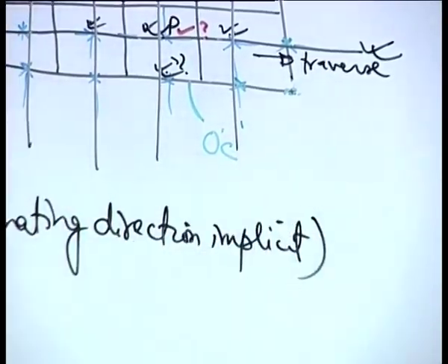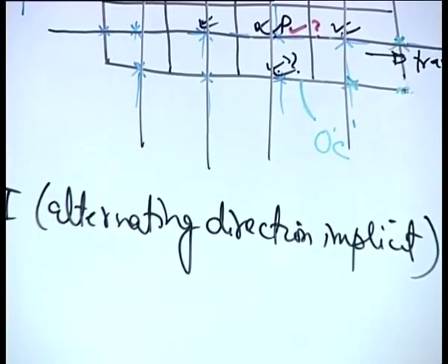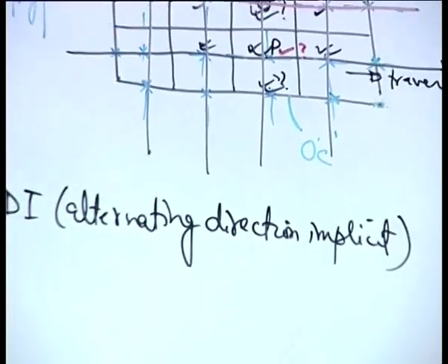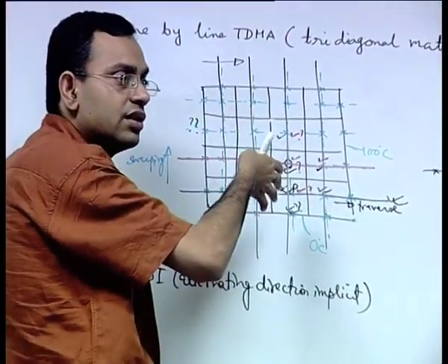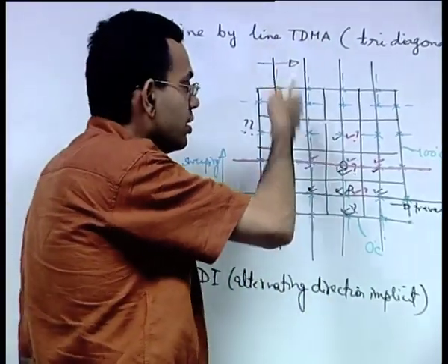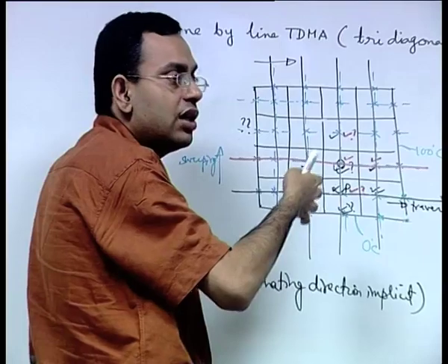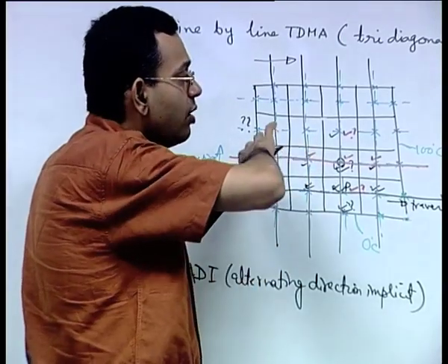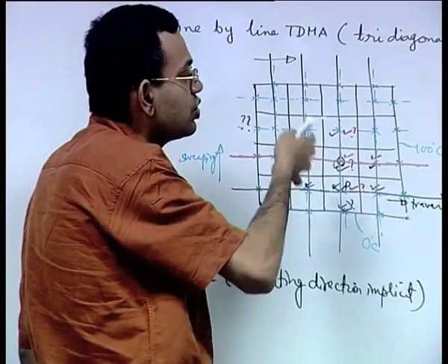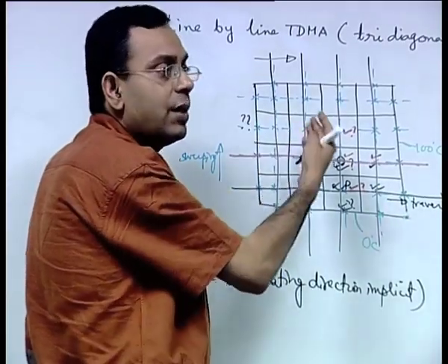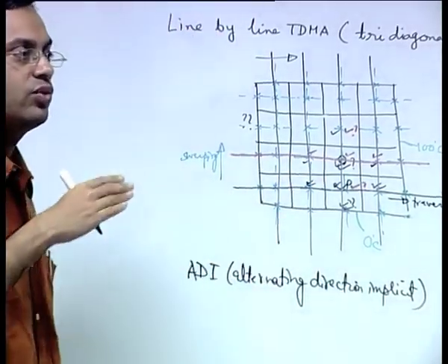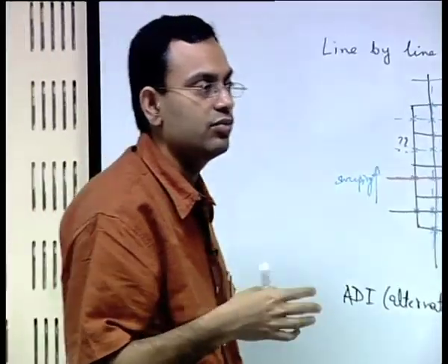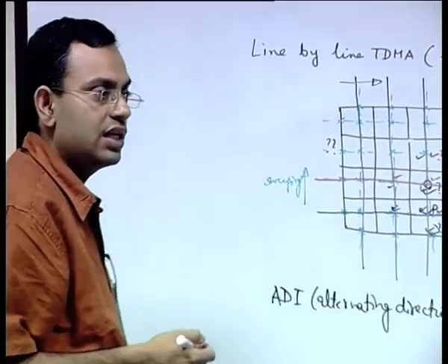The idea of this is straightforward. The objective is, if you alternate the directions of your solution, your use of the TDMA or the elimination method, then you allow the conditions at all the boundaries to propagate in an equally effective manner to inside of the domain, rather than having a bias towards certain boundary, which is not the case that you want.